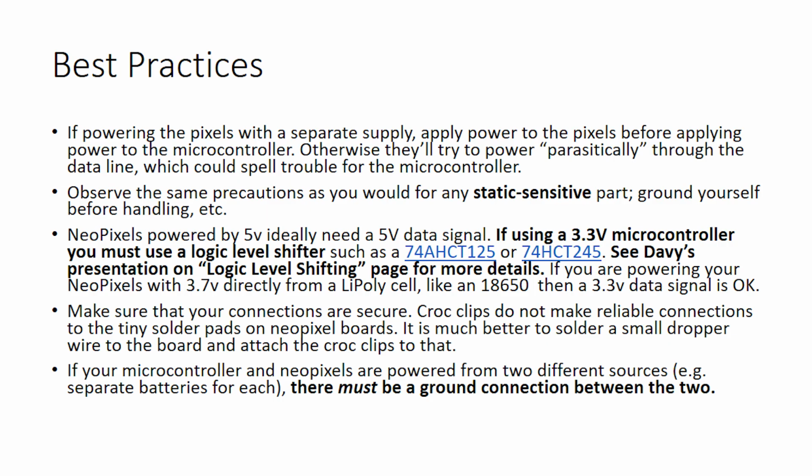If you accidentally put power on your microcontroller and you haven't powered the NeoPixels, they will try and suck power through the data line. And so the NeoPixel strip will suddenly try to take all its power out of the pin of the microcontroller, but not the power pin of the microcontroller, out of the I/O pin of the microcontroller.